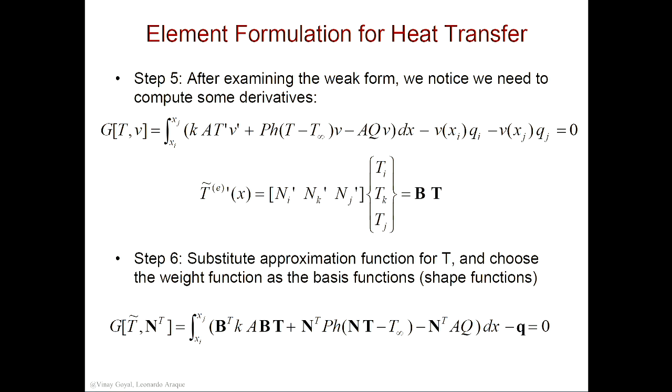Okay? And then when I look in here, for T, it's easy. For T, it's just N times T, which was in the previous page. N times T. For V, I have to make it N transpose. So anytime you make a transpose, just bring it at the beginning. Okay? So you can keep the matrix being 3 by 3. You know you're wrong if you put this one here really quickly. If I make it N times N transpose, it's wrong because then I get a 1 by 1 matrix. So just keep that in your mind as you're working the problem. All right, so that's my matrix.